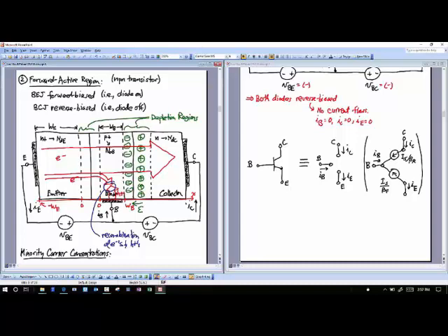And you can design your device to try to decrease it as much as possible. I'll show you an equation that you can use to tell me what you need in the physics to decrease this base current there. Okay? But if you had no recombination, you'd be overjoyed because then all your electrons would make it to the collector, and that, in fact, is what a transistor is supposed to do. Right? It's supposed to get current from one side to the other without losing any of it. The MOS does that without losing any of it, but the bipolar does not.